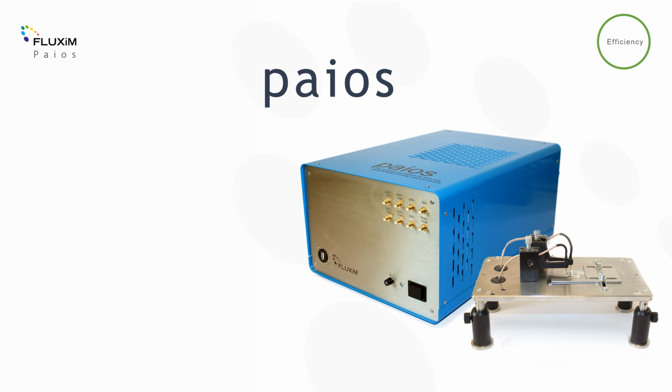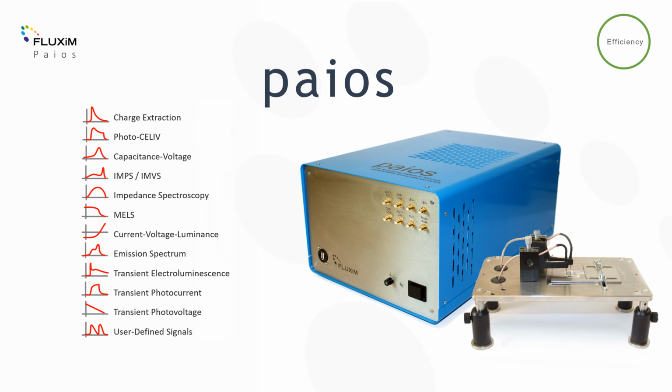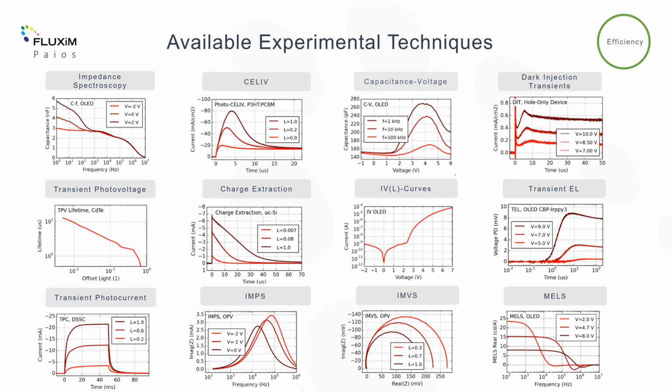Fluxim has resolved these limitations by integrating a number of characterizations into a single instrument called PIOS. PIOS comes with a probe station and the full system is calibrated down to the probe tip to assure trusted collection of experimental data. You'll get consistent measurements and move from the initial implementation of the measurement through to the preparation of the final graph within the PIOS software. With PIOS, you can perform a set of pre-installed experiments, or you can define your own tests. Characterizations can be performed in DC, AC, transient voltage and current, in dark or under different light intensities.